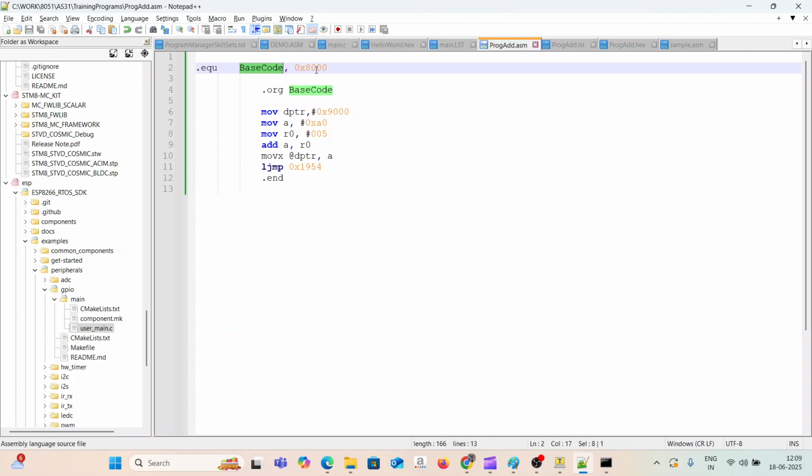I'm using a single board computer for 8051, where the external memory is mapped at address 8000 hex, it is an external RAM, and the single board computer contains a monitor program, which runs from the internal flash of the 8052 microcontroller. So that gives me many options to download the code and run. We'll see that in a short time.